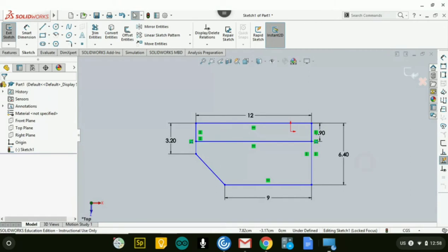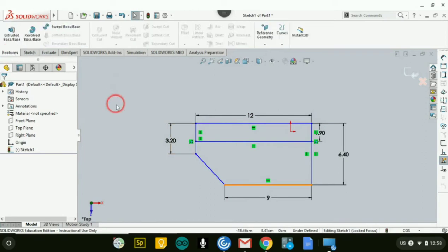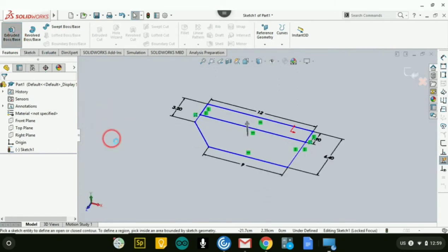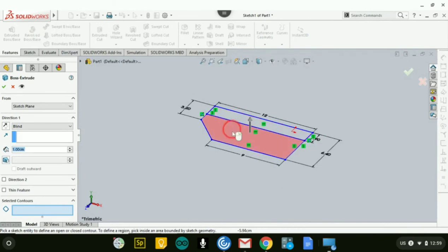We have the same exact sketch of our top view in our 3D view drawing now in SOLIDWORKS. So now that we have our 2D object, we can now make this into a 3-dimensional object with a tool. So if we go to our Features tab, go ahead and click it. We're going to use this tool up in the top left corner called Extruded Boss Base, sorry. And what this tool does is it allows us to pick a face or a piece of our object if it's sectioned off like how we have it.